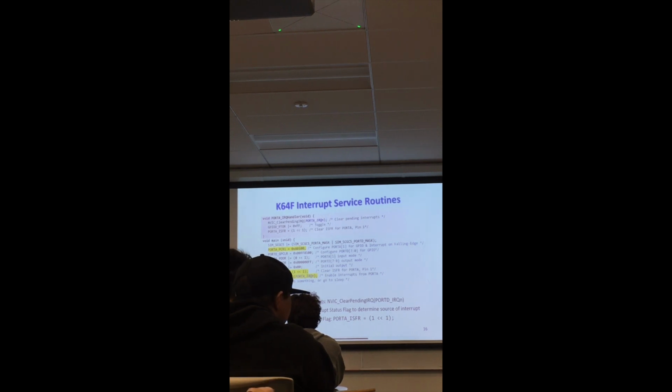So, interrupt service requests. You set up all pins for inputs, outputs, set up the clock and so on. What is critical is that first you have to initialize the interrupt vector and enable interrupts. Remember, once you are configuring interrupts, make sure that your system doesn't process any interrupts. So if you want to reconfigure some interrupt, disable all interrupts.